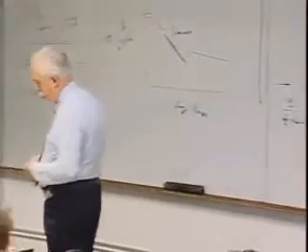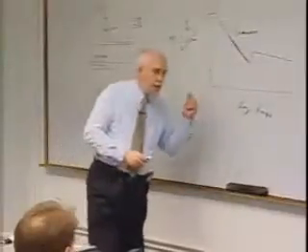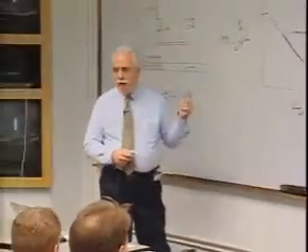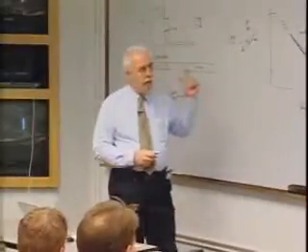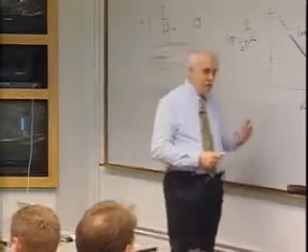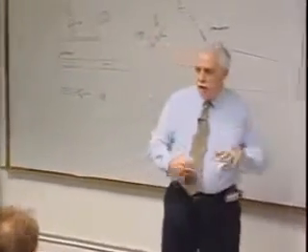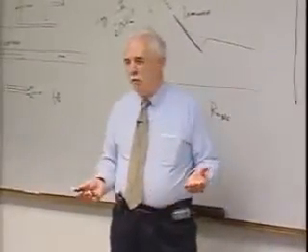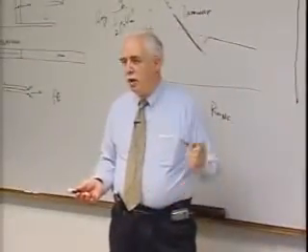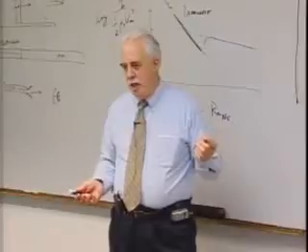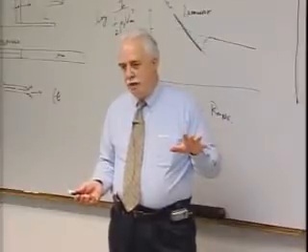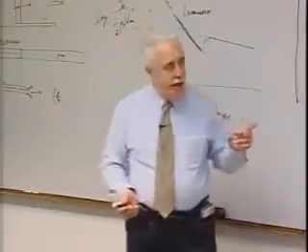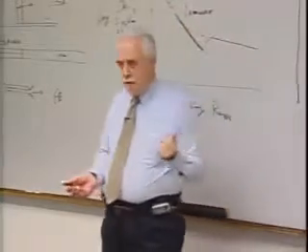What we learned was that energy is extremely important, the enthalpy. And frankly, going beyond Mach 8, which is what everybody tried to do, getting to higher and higher Mach number, really doesn't work too well in a ground facility when you're talking about heating distribution. It does give you Mach number effects, okay? But the gas is not at all like what you have in flight.